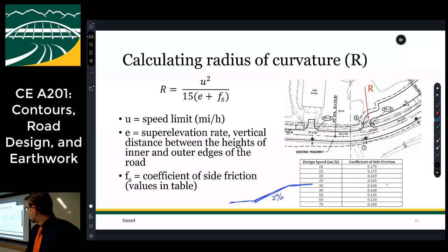And so you can kind of see the number goes at slow speeds from around 0.17 to fast speeds around 0.12, which is kind of interesting because it means that you have 2 variables in here that are based on speed, and you could probably make one a function of the other, but traffic people like charts for some reason. I don't see why you couldn't make this just math, but for some reason it's always a chart.